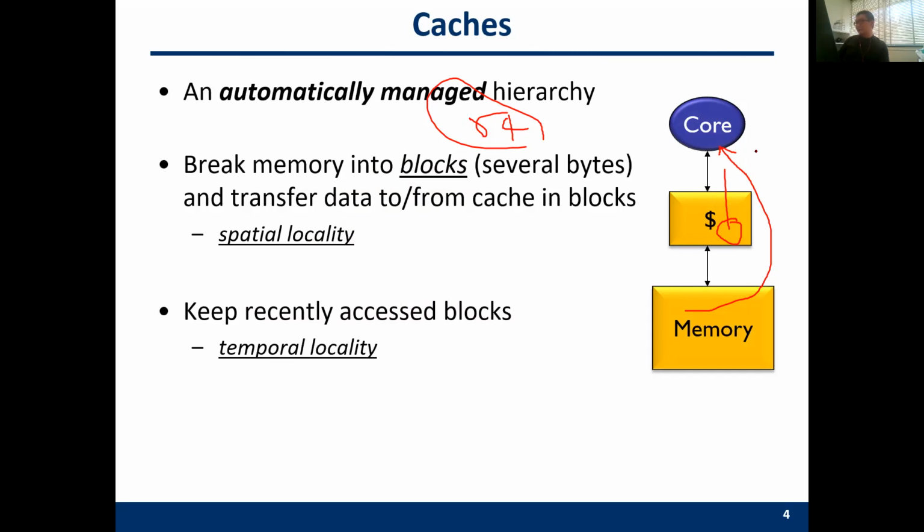Instead of fetching it from the main memory again, we can read the data from the cache. And compared to the DRAM, of course, the on-chip cache is faster. So in this way, we can save some latency cost. This is so-called temporal locality, because in different cycles we request the same data.